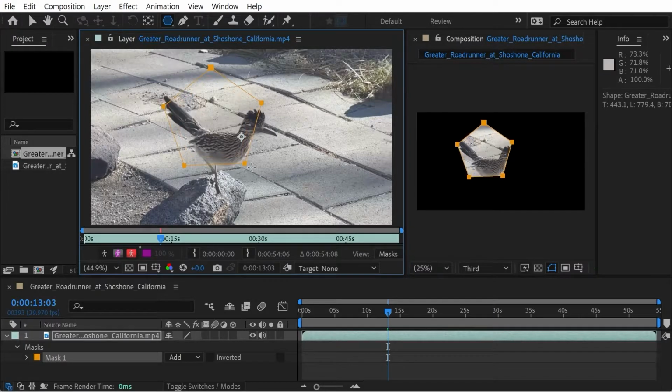So when creating a polygon, what we can actually do is we can press the arrow key. So up and down is actually going to increase the number of sides. So we can get more sides, and then left and right is going to change the rounding. So you see we can turn it into a circle with more points. So you could create something like this. You can go beyond, more sides. So you could do some interesting stuff with that.